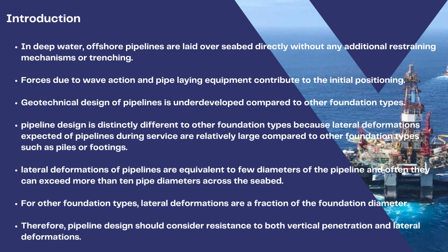Forces due to wave action and pipe-laying equipment contribute to the initial positioning. Geotechnical design of pipelines is underdeveloped compared to other foundation types. Pipeline design is different to other foundation types because the lateral deformations of pipelines are very large compared to other foundation types such as piles and shallow foundations.